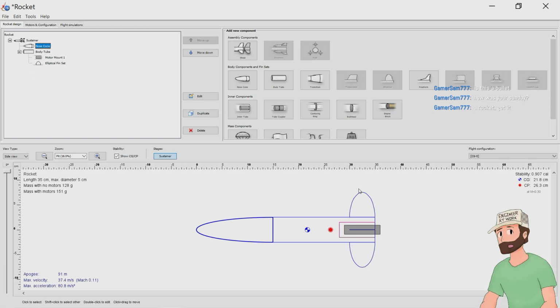If you do it too much, then it overcorrects, and as it's going up, it does kind of a wobbling motion. If you don't do it enough, then your rocket tumbles as it goes up, which is no bueno. And you can fly rockets that are statically unstable as long as you have an active control system that is fast enough to compensate for that. But we're going low tech first. It's good to start low tech and then work your way up.